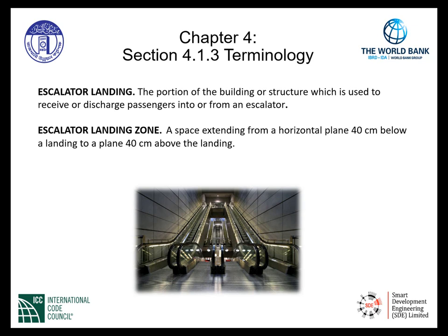The other definition is escalator landing zone. This is a space extending from a horizontal plane 40 centimeters below a landing to a plane 40 centimeters above the landing.